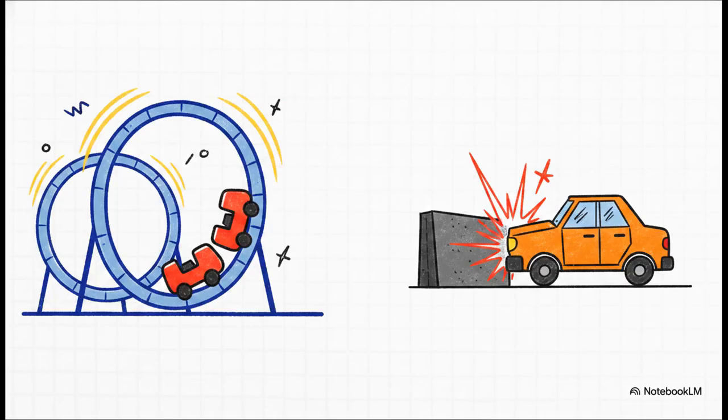And from that bedrock, engineers expand into advanced dynamics. We're talking the work-energy theorem, impulse momentum, and the conservation of mechanical energy. This is the heavy-lifting math that evaluates massive energy transformations. It's how we ensure a car safely crumples in a crash test, or how we calculate those thrilling yet perfectly safe G-forces you survive on a roller coaster.